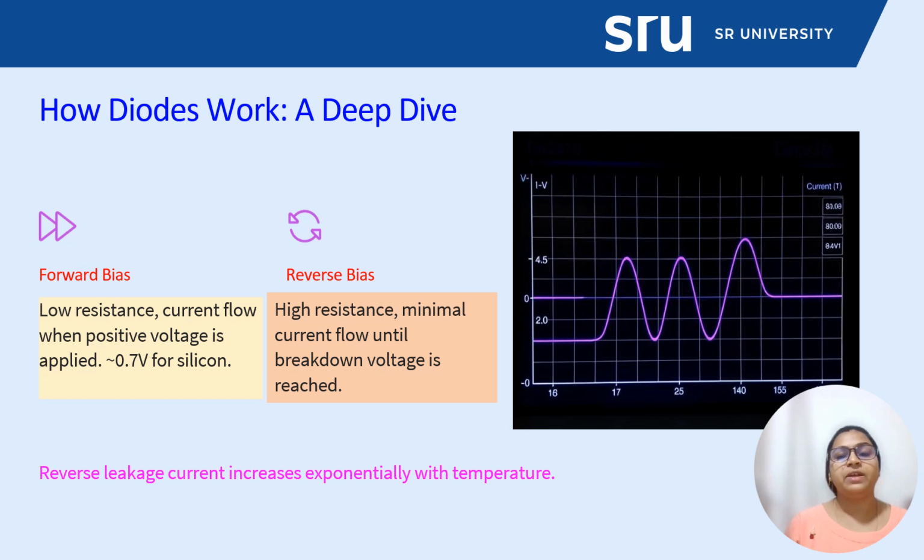Carrier dynamics are driven by diffusion plus drift, and capacitance varies with the bias, which is crucial in high-speed applications. Its real effects are in series resistance, leakage, breakdown voltage, breakdown region, and it has an effect on temperature.